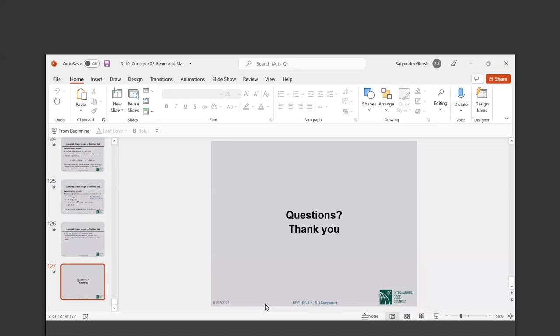You need skin reinforcement. But the horizontal shear reinforcement in a deep beam is mandatory. Yes. Yeah, Dr. Ghosh, you are right. It is 900 mm. And that thing is also mentioned in BNBC 9.5.3.2. So I'm just giving an extra information.